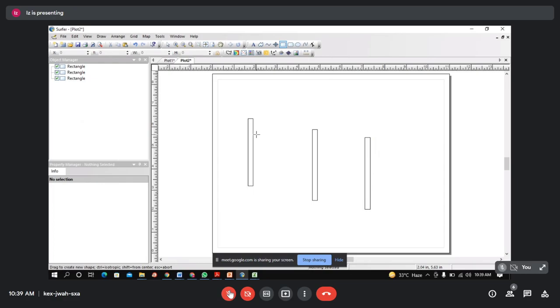So these were the three wells drilled in a line. So using these three lithologs, you can draw a lithological cross section, right? So how will you do it? Of course, you will scale it. So this will be the vertical scale. This is the vertical scale with respect to mean sea level.